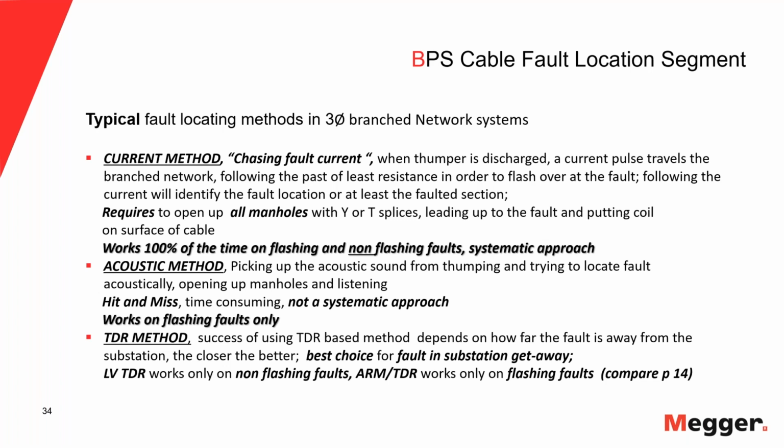There might be times you get really lucky and you can hear a fault with the second method that I call here out as the acoustic method. You can. I will not deny that. But many times I have seen the opposite, where you cannot pick a good acoustic signal up and you are just scrambling and cannot make ends meet. So this method to chase the fault current is a systematic approach that will get you to the fault. So let's talk about that.